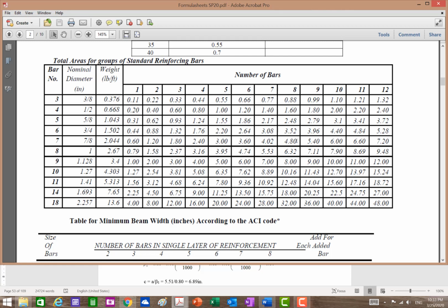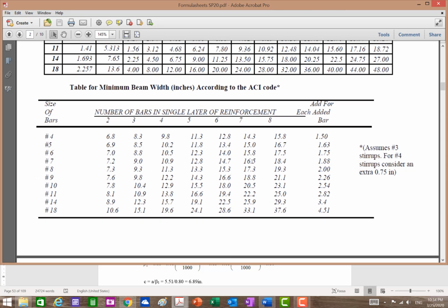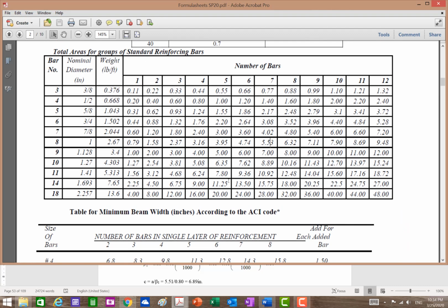So I said, okay, well, I need fewer bars. If I use fewer bars that are close to my value, I can use 635. Oh, well, 624 is closer. Okay, I can try 6, but that would be 6 number 9s. Okay, let's see 6 number 9s. Ooh, it's also greater than 16. So 6 number 9s doesn't work. So that was out. So now we keep moving, and we get into this area.